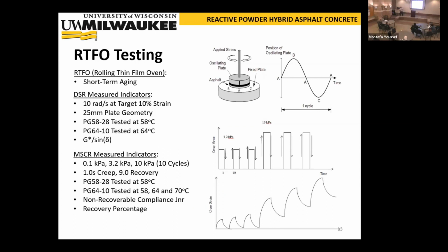We wanted to also characterize the final product in terms of its damage resistance. So we applied a damage-controlled or damage-influenced test called the MSCR test, multiple stress creep and recovery, where you expose the material to cycles of creep and rest to see the level of recovery of the deformation, and then separate the results into what is permanent deformation or damage and what's recoverable deformation. This test is done at high temperature, which is a good indicator of the behavior of this material in the summertime.